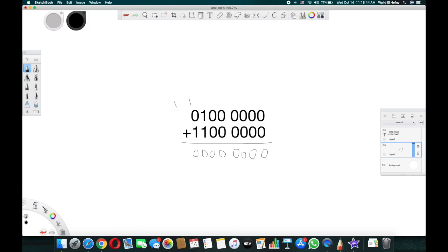Okay, this is perfect because this is actually the answer. However, at the end we have a carry. Is this carry an overflow bit? As I told you, no, it is never an overflow bit. It is only a carry bit. If we perform our hack, XORing the last two carries, 1 XORed with 1 results in 0. Therefore, the overflow flag will be 0.